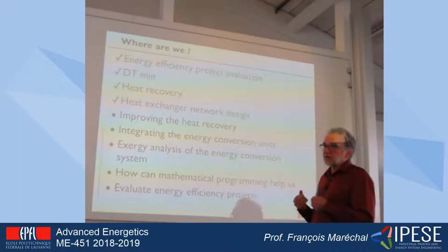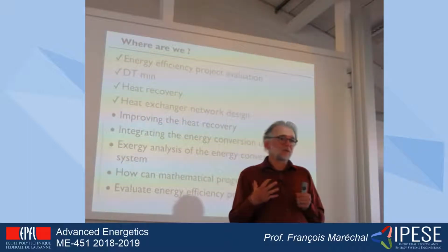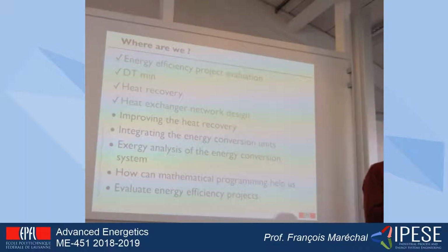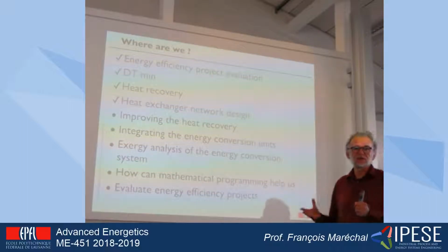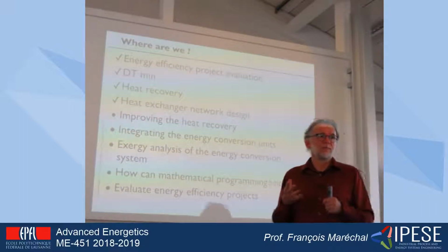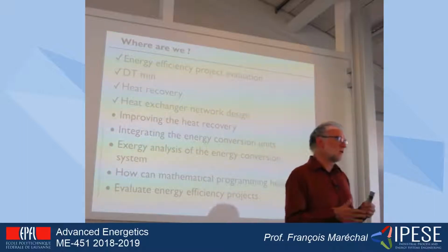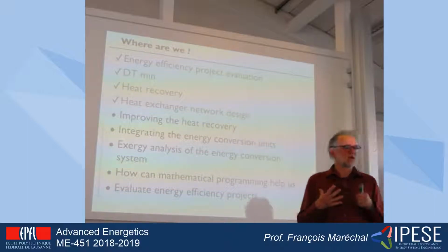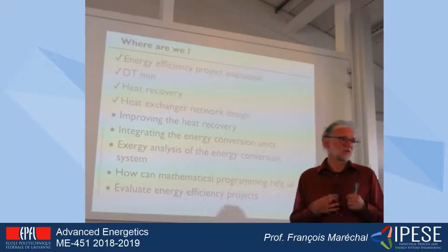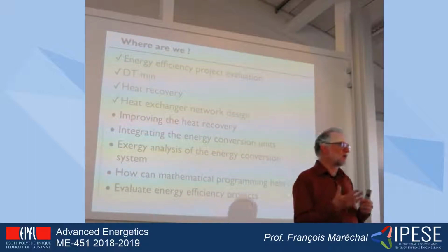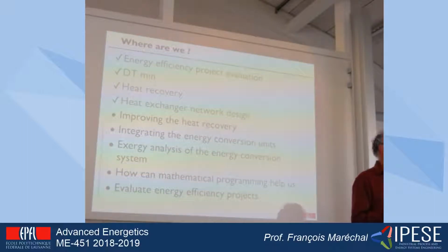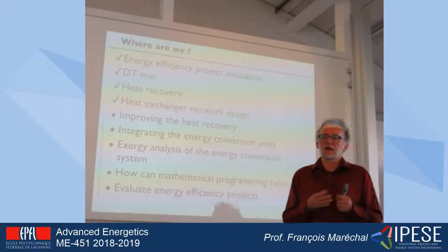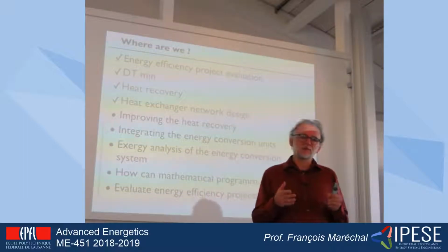And from there, we have also been able to define a method that allowed us to create the heat exchanger network that does the targeted heat recovery by matching the hot streams with the cold streams, with a list of feasibility rules that were allowing us to finally define the design, so the structure of the heat exchanger network, with the appropriate splitting of the streams and the appropriate matching in such a way that we were realizing the heat recovery with the minimum number of units.